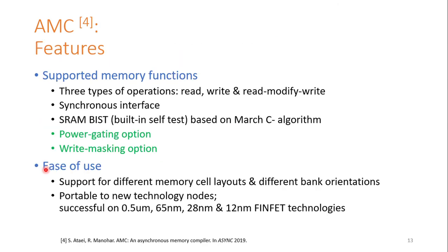AMC supports common memory functions like read, write, and read-modify-write. It also provides a synchronous interface so that you can include asynchronous memory in clocked designs by wrapping asynchronous memory in this synchronous interface. AMC also provides SRAM built-in self-test, power gating, and write masking options.